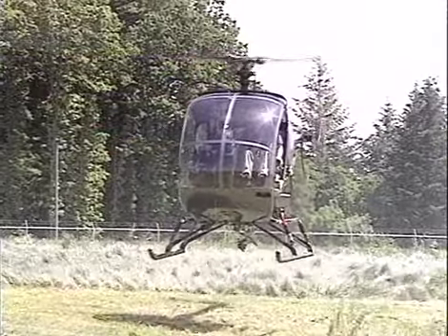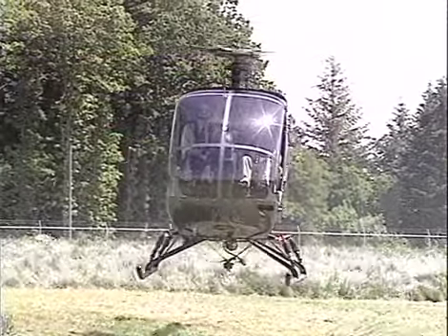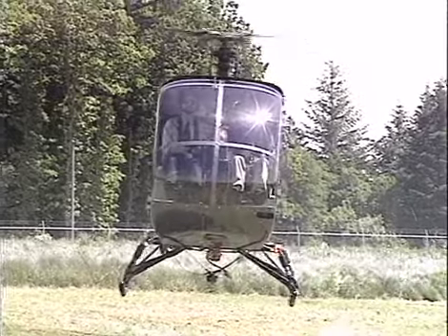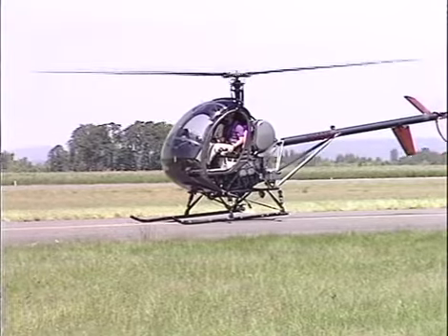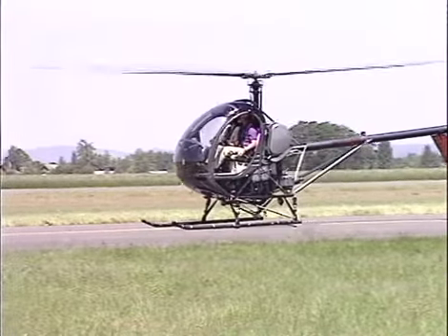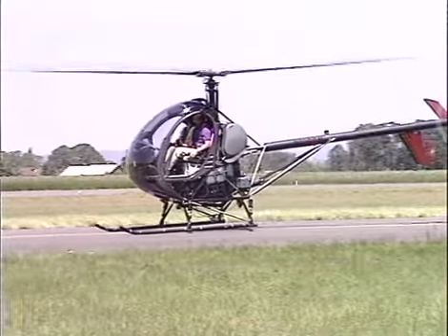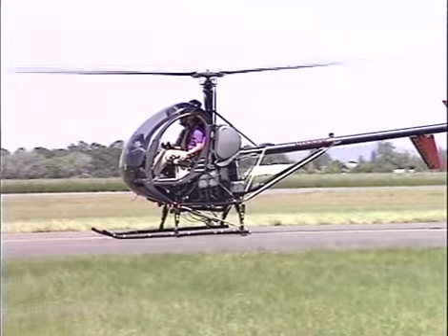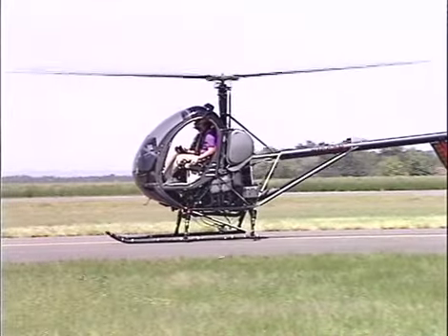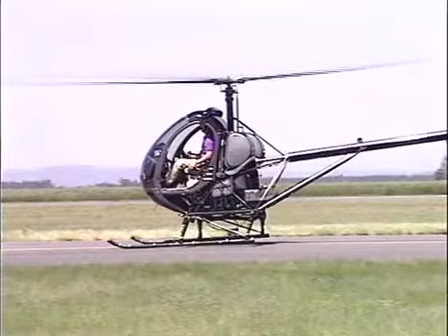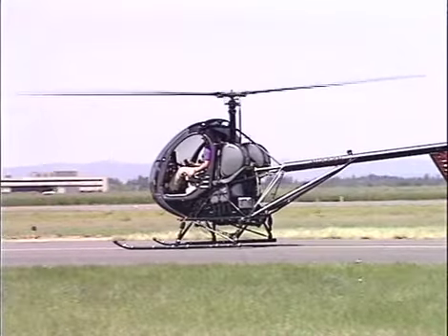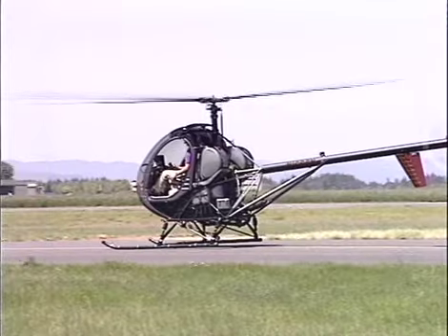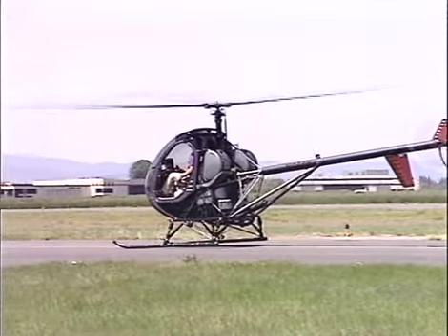A helicopter with skids for landing gear usually hover taxis several feet above the ground. Taxiing while the helicopter is in contact with the ground is called a surface taxi. Usually only wheeled helicopters surface taxi. However, even helicopters with skids will surface taxi in some situations, such as when rotor downwash in a hover might cause damage to other aircraft in the vicinity, or when the helicopter's gross weight is high.